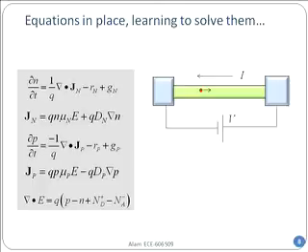We know the drift and diffusion equations. We know the continuity equation we just derived. Now, if you have to solve it, there will be a problem. Do you see why there might be a problem? First of all, how many unknowns do I have here, do you think? I have 3 unknowns. Do you see? Electron number, hole number, and the electric field or potential.